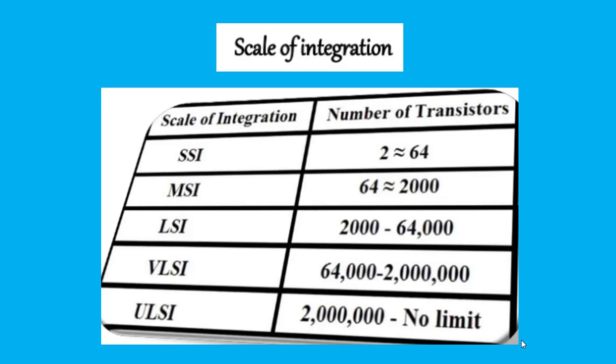Levels of integration. Digital ICs are often categorized according to their circuit complexity as measured by the number of equivalent logic gates on the substrate. There are currently 5 standard levels of complexity. Small-scale integration, SSI. These are the least complex digital ICs, with less than 12 gate circuits on a single chip. Logic gates and flip-flops belong to this category.